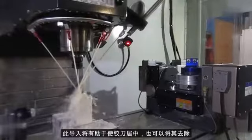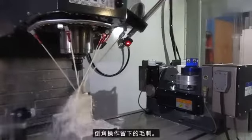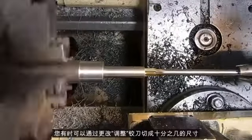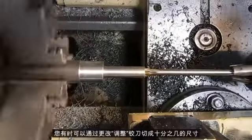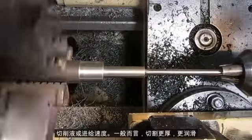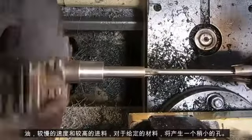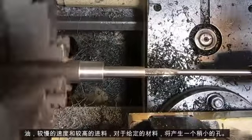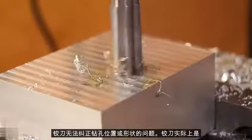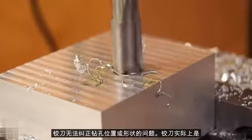This lead-in will help center the reamer and will also allow it to remove the small burr left by the chamfering operation. You can sometimes adjust the size that the reamer cuts by a few tenths just by changing the cutting fluid or the feed-in speed. Generally speaking, a thicker, more lubricious cutting oil, slower speed, and higher feed will produce a slightly smaller hole for a given material. A reamer cannot correct issues with location or form on drilled holes.